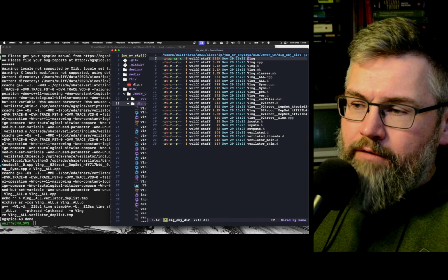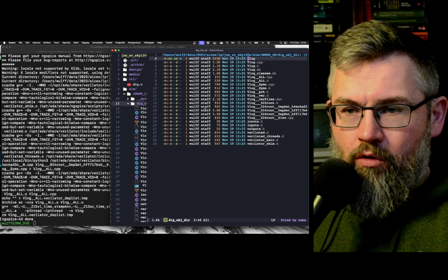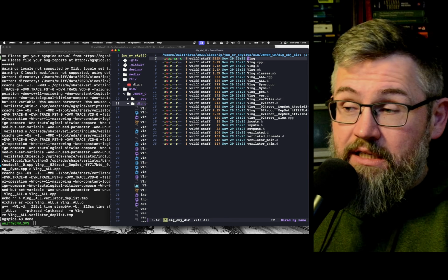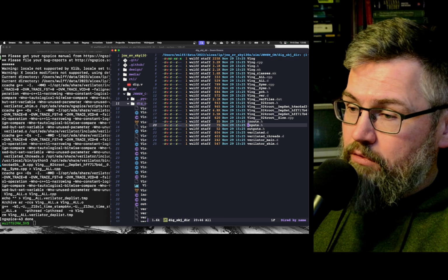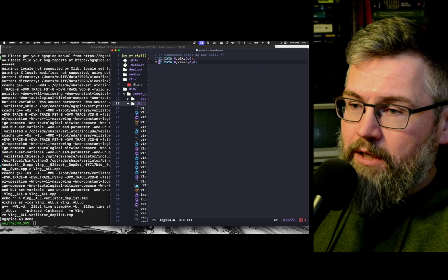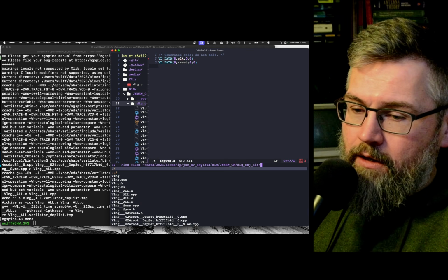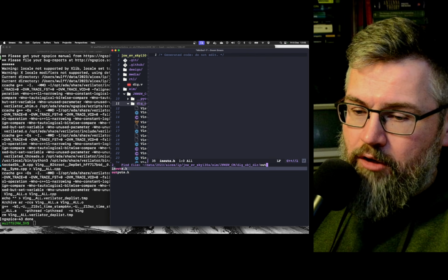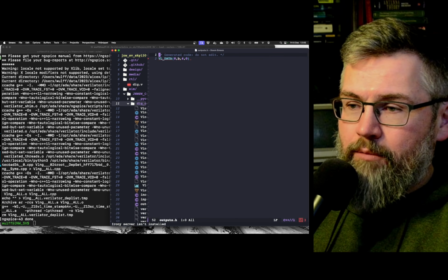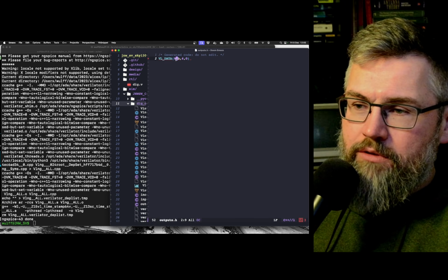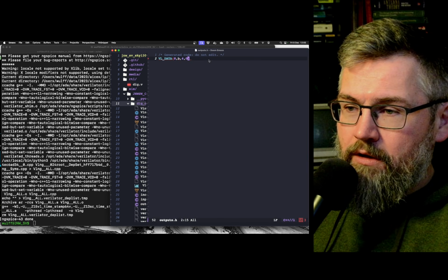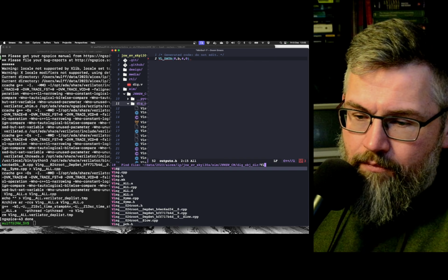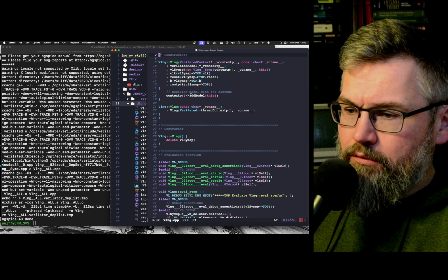Verilator translates your digital design into C code. If we look at, for example, inputs, we will recognize we have the clock and the reset. We have the outputs, where there is an 8-bit bus internally, but it's a 5-bit bus. That is the B output. And I guess there will be some Verilog code here.